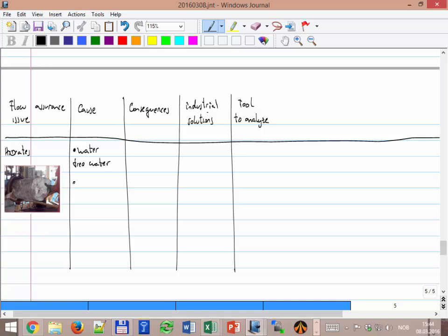Okay, in liquid form. Then you have to have light hydrocarbon molecules. Remember that these molecules want to be inside this box, so they have to be small enough to fit and be comfortable. If it's a big chain, a big molecule, usually you don't get formation of hydrates.